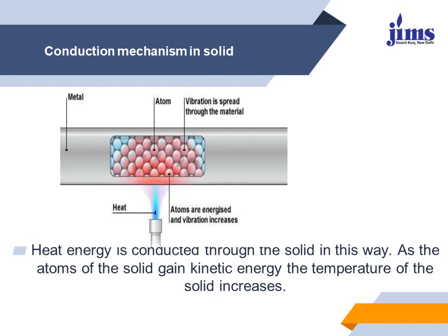In lattice vibration, the faster moving particles or atoms in the hotter part of a body transfer heat by imparting some of their energy to adjacent molecules. The second one is transport of free electrons, where free electrons provide an energy flux in the direction of decreasing temperature.